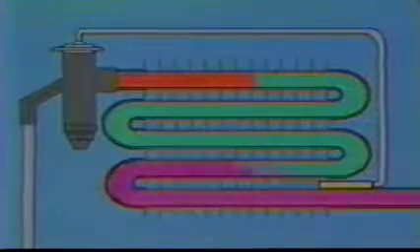The important point is that the extra heat that is in a high temperature inlet liquid must first be removed upon entering the evaporator. That heat removal is inefficient and robs the system of capacity. For maximum capacity, the liquid line temperature should be as low as possible.